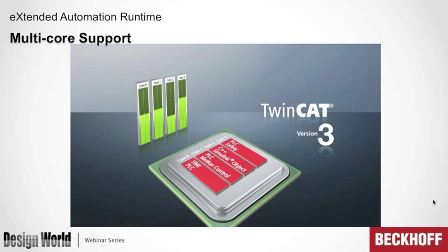This is a popular item. Now with multiple cores, what's interesting is for years we've been doing motion, we've been doing the PLC, we've been doing the HMI, we've been doing them on one core. With the recent advances in multiple cores, we've kind of gone back to, this is interesting. And now it's possible to split up. Maybe I can run 80 axes on one core, just devote that all to motion control. Now maybe I put my HMI on one core, and maybe I do all my PLC on another. So it just multiplied what can be done, what the control system can do.